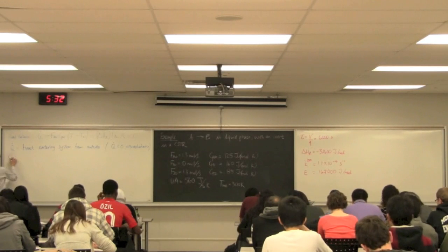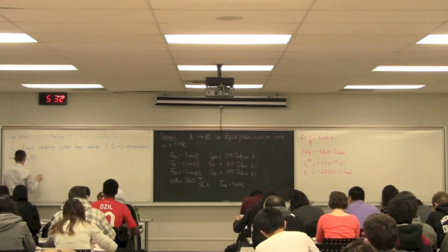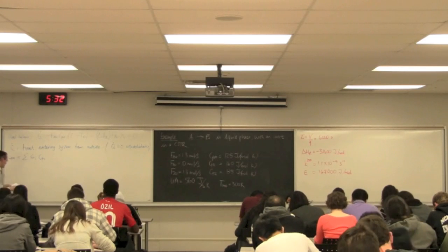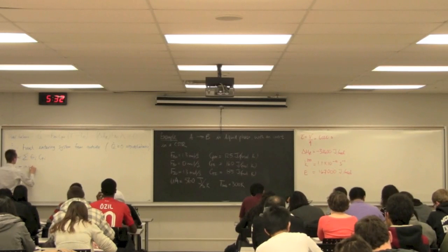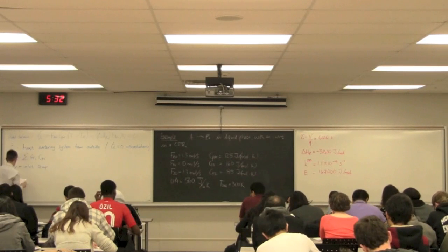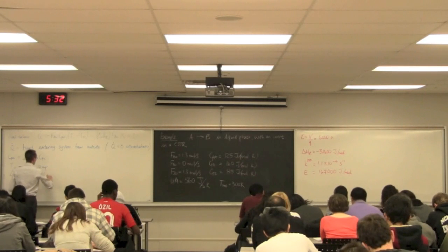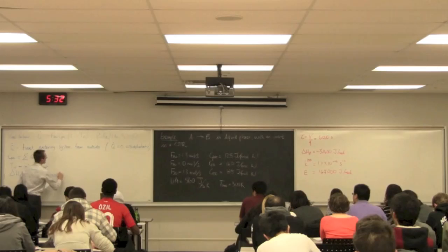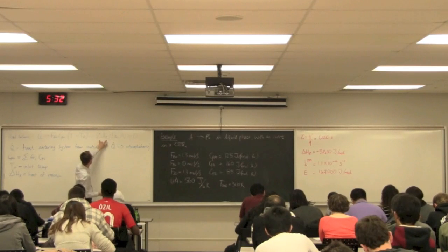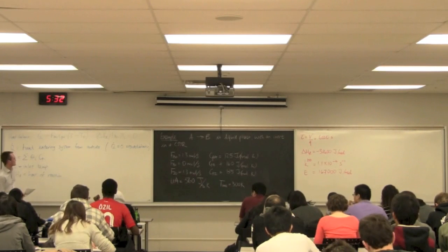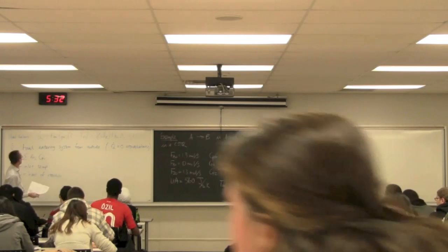Cp0 is a weighted sum of the heat capacities, weighted by theta_i, Cp_i. T is the system temperature, T0 is the inlet temperature, and delta H_R is the heat of reaction. When we've got negative delta H_R here, it's not implying anything other than take the heat of reaction and multiply it by a negative sign. So for example, in an exothermic reaction, we have a negative inside the bracket and a negative outside the bracket as well.